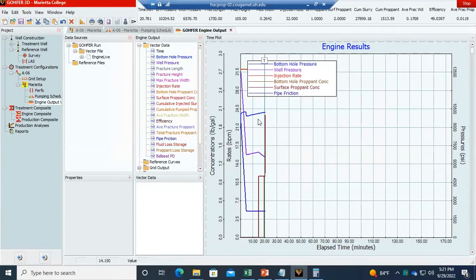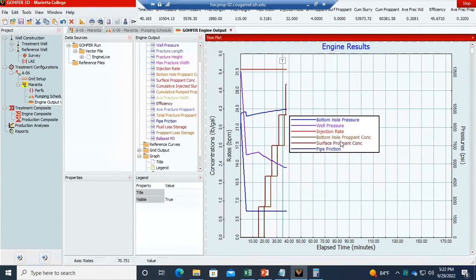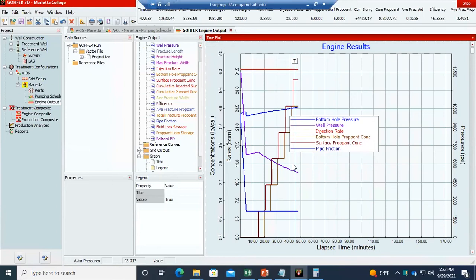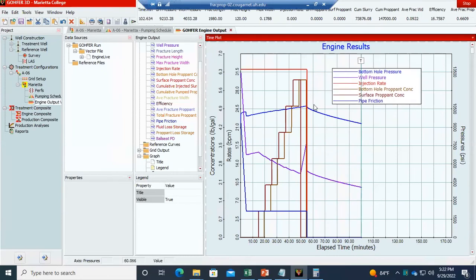Now this is the bottom hole pressure. This is the surface pressure. It finished the bed. Start proppant ramping. The rate is 32 barrel per minute. There is our frac job continuing to be simulated. So the surface pressure is around 7,000 psi. The pressure is around 10,500 psi.